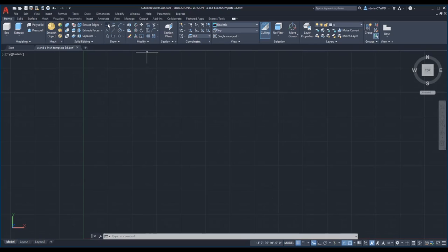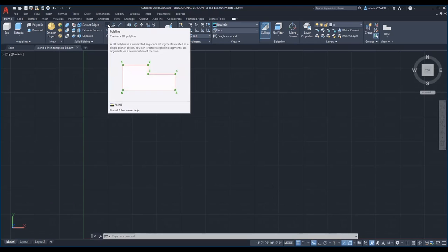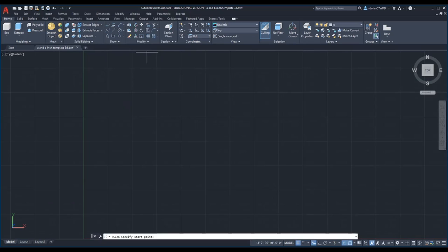All right, we're going to draw a polyline, the outline of the house. So I'm going to go to polyline, and I'm going to start at the coordinates 25 feet. I can put inches in here, but if there are no inches, I can just pick comma. 25 feet, comma 10 feet, and make sure I put the foot symbol. So there you'll see now I have my start place. In the book that is the start point on page 19.